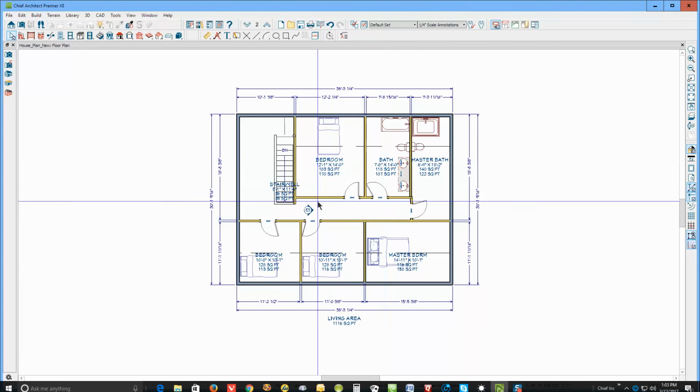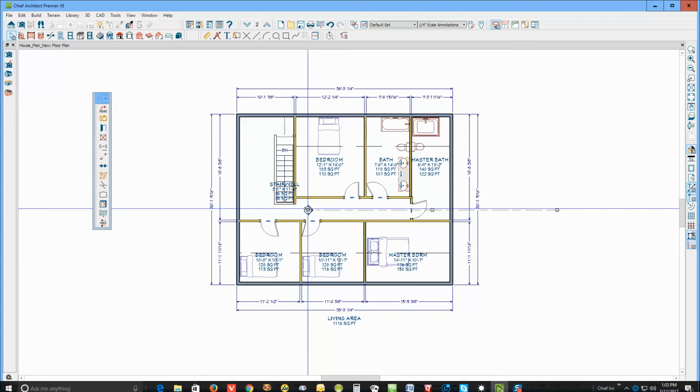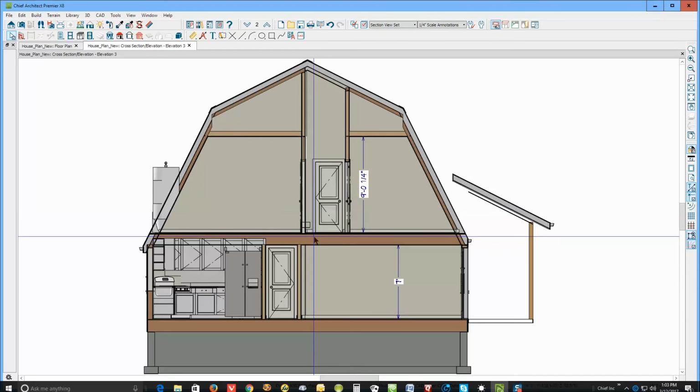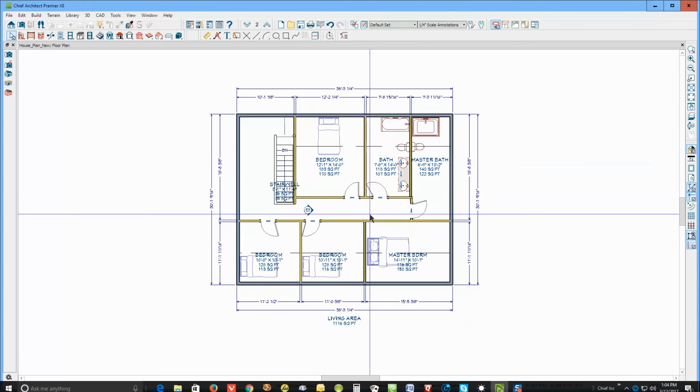Now, let's take a look at this. Since I've done that, well, that floor platform didn't move. Now this changed up here on the second floor, but I haven't even done the second floor yet, so I'm not really interested in this figure. I'm interested in, this needs to be up at the 9 foot level, unless you're Munchkins, and a Munchkin's going to live in this house.